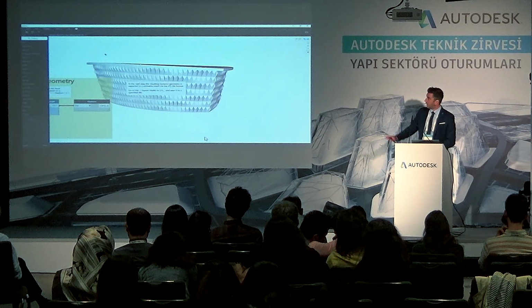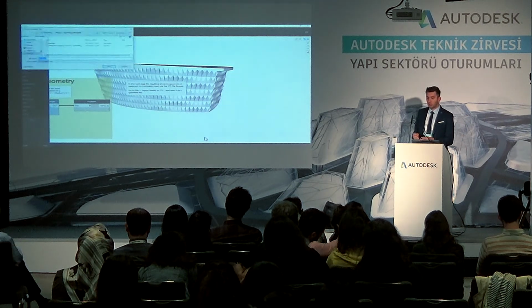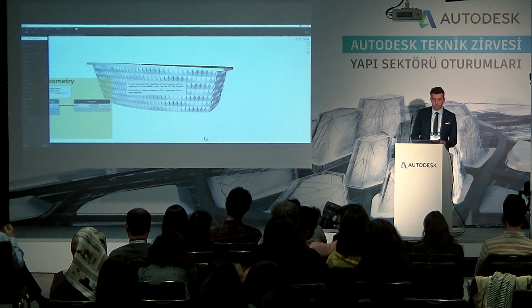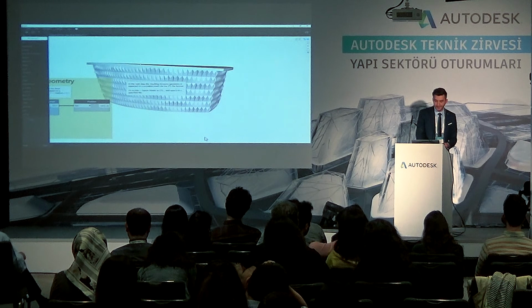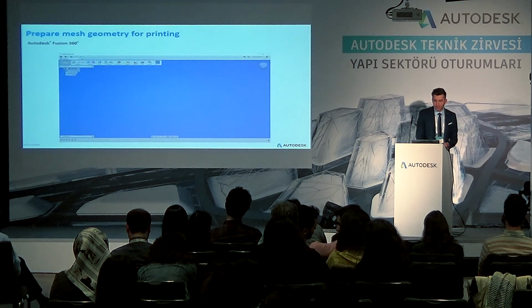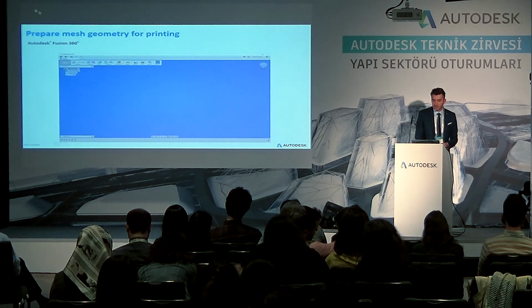The first example is just using the concept geometry, like the shape of the airport, but we can also print the facade. So if you want to focus on the facade, we can again export to STL format. And now we can use Dynamo to export to STL. Dynamo is very powerful to export this kind of format. And again, we are doing the same process, the same steps.